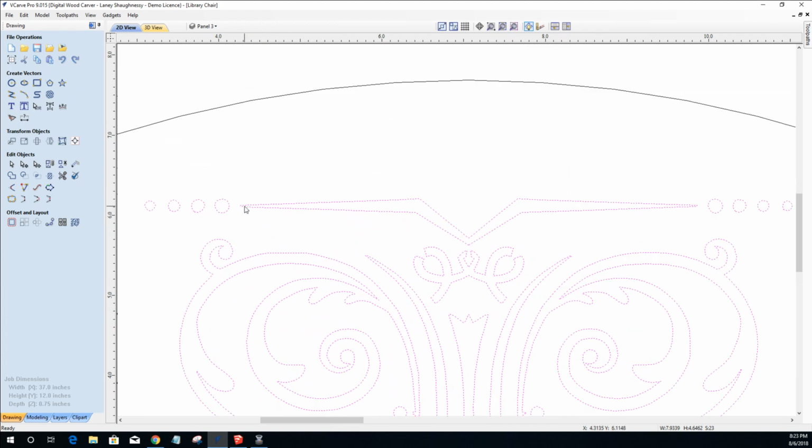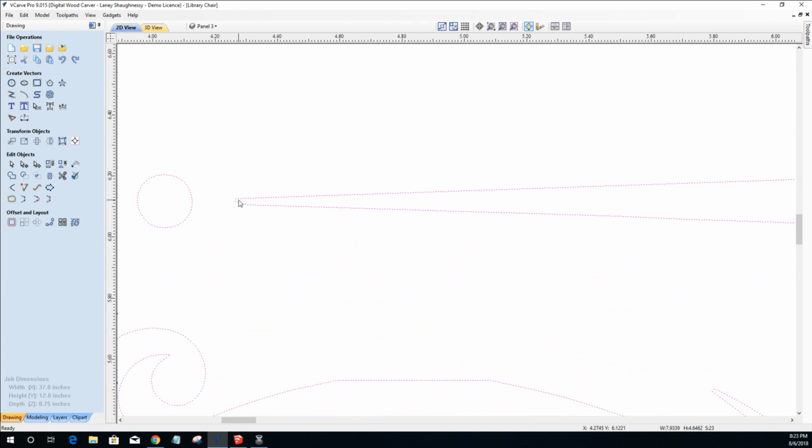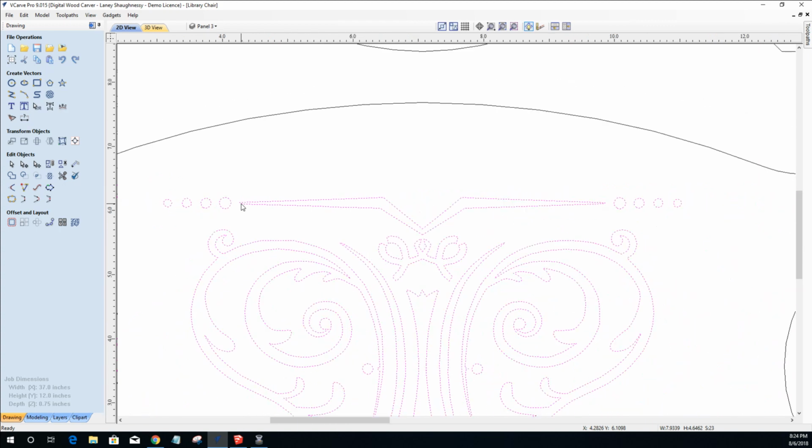Now my end mill is not going to go all the way to the end of this part here. I could use my tapered ball nose end mill, my 32nd or something, which can really get into tight areas and it can get deep. I can cut through my 3/4 inch material with it. I might be able to use that. But let's look at what my 1/8 inch end mill will do and how far it's going to get me.